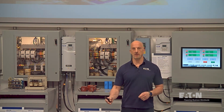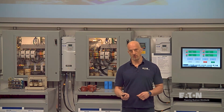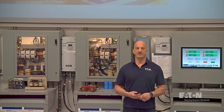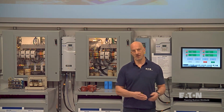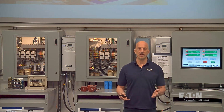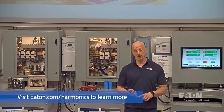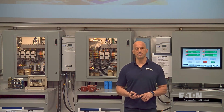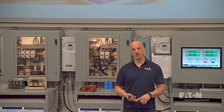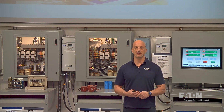But in the same way, you could get rid of a power factor penalty and save 20% of the money for your bill. You can relieve some of the money when you do power factor correction with harmonic filters, but not the harmonic part of it. So again, it's all related, but just make sure you understand that the part on your bill that you're going to save is losses or power factor compensation. And because harmonic filters do both power factor and harmonics, sometimes there's money to be saved, but not from the actual kilowatts or kilowatt hours. Seems a little confusing, but it's really not that bad if you think through it.